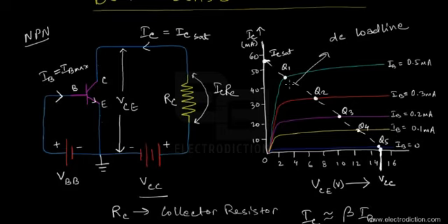Now these particular points of the transistor output curves with which the DC load line intersects represent the various Q points, or the operating points. So we will basically call them operating points, or Q points. They're also popularly known as Q points. So these are the particular points where we need to keep the transistor, or rather the BJT, biased, so that we have a particular value.